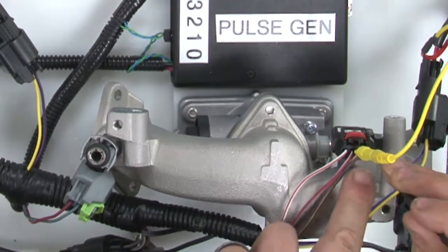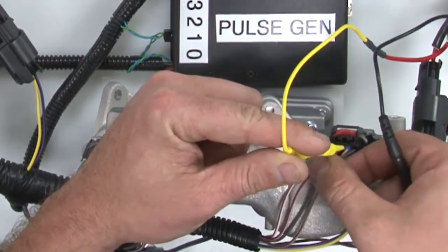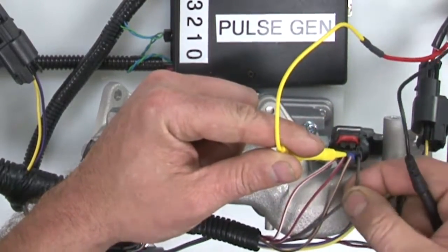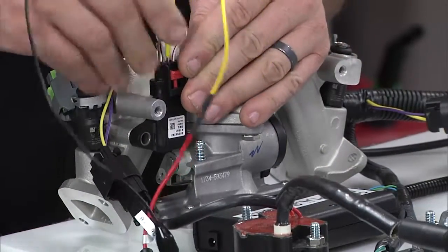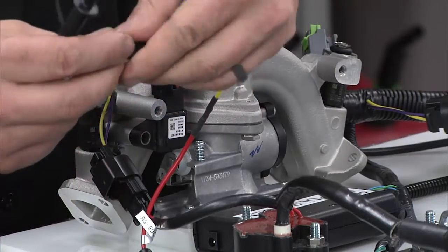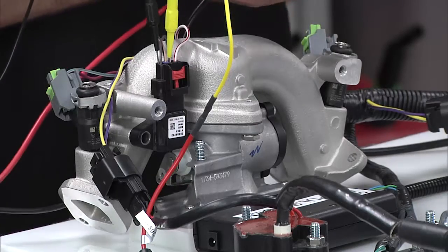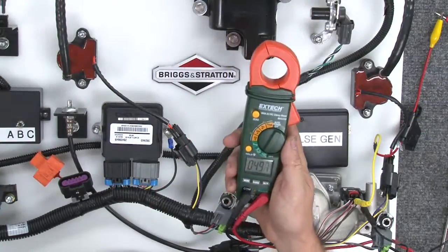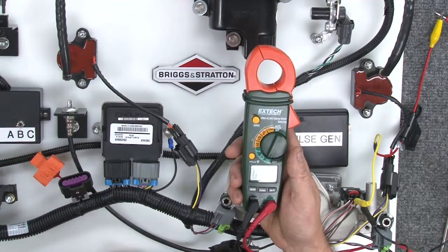The next thing I'm going to do is I'm going to back probe the dark brown wire on the edge over here. It's the dark brown one, not to be confused with the tan one, dark brown. That way I complete my circuit here, hook that one up to my black meter lead, and then I'm going to turn my meter on. Now when I turn the meter on, I should see almost 5 volts, and I do, which is good. That tells us that we have 5 volt reference there.